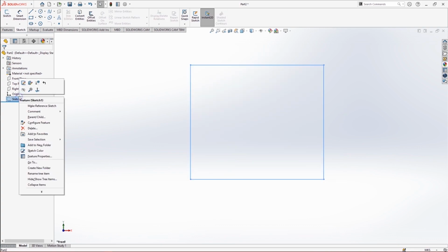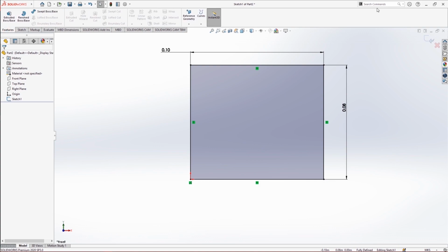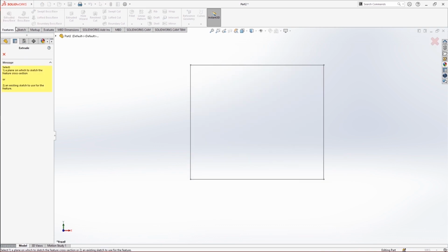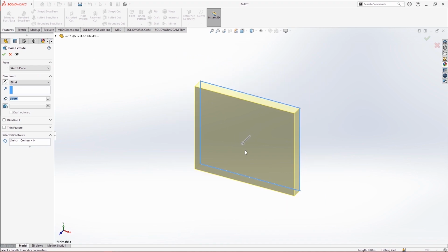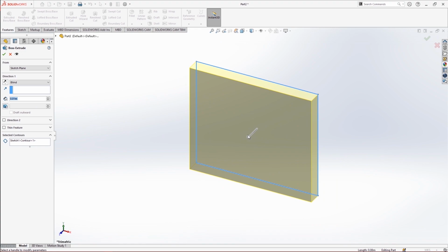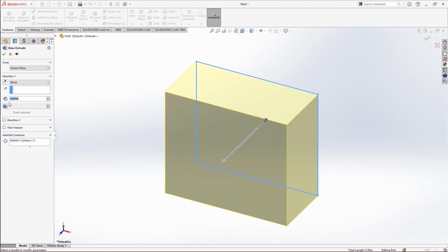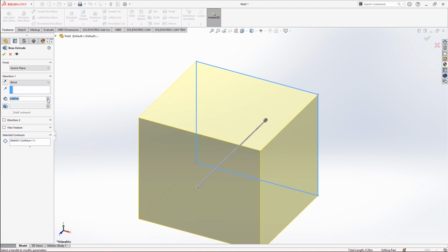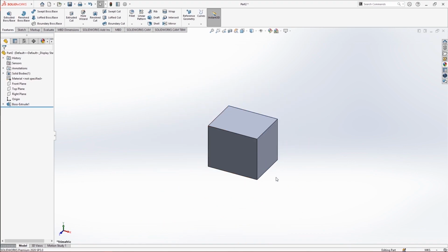Let's just go into 3D and make our first 3D. Go to edit sketch, and you can also make 3D using exiting. Okay, let's just exit and go to extruded boss and select this particular sketch, and you can see we are in extrude mode. So you can set the dimensions using this particular handle, or you can set the values at what value will be the extrude. You can set your value here, and we are done with. So we have our first 3D model.